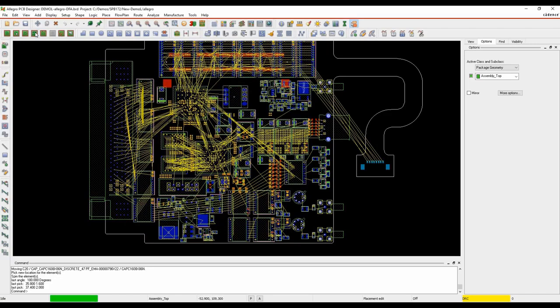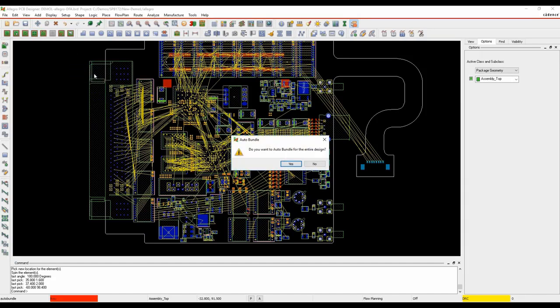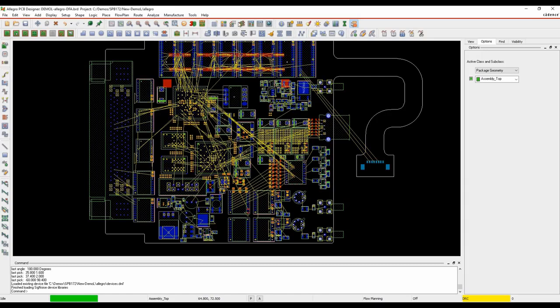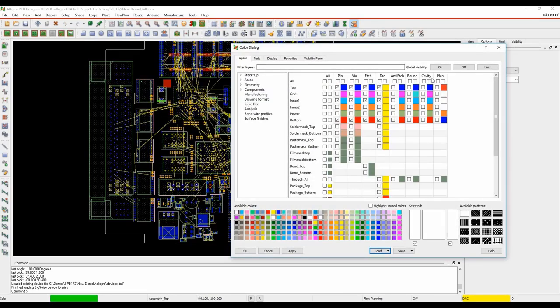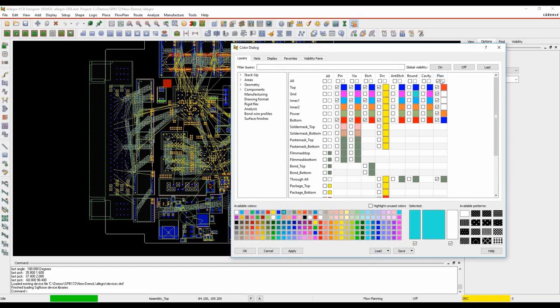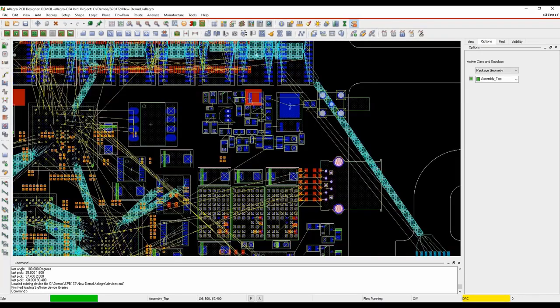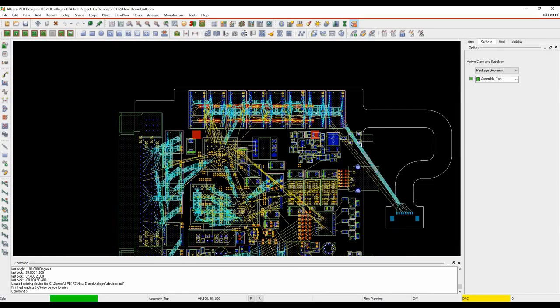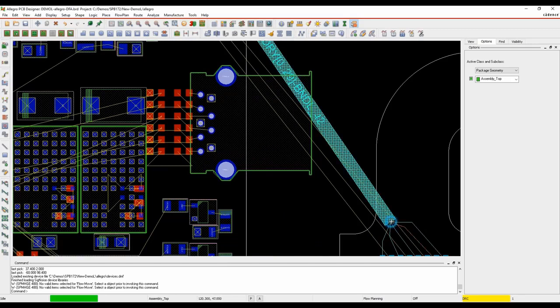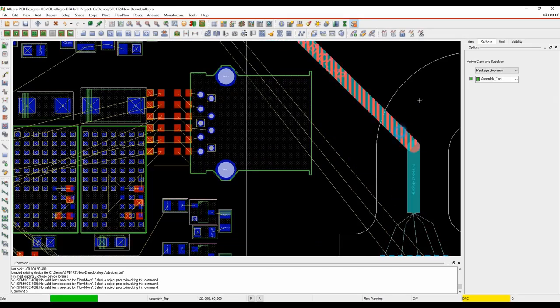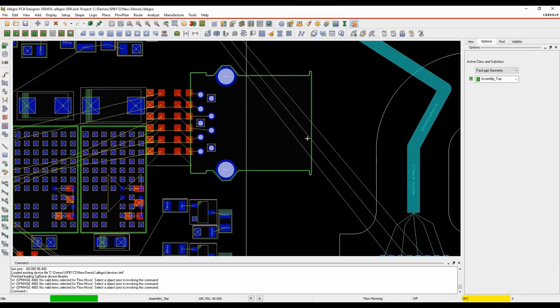But what we'll do is we'll go into IFP mode, or Interactive Flow Planning mode, and then I can just right click and auto bundle all, and we'll say yes to that, and all the bundles go. And if we go to the colours, there's now something called a plan. Let's specify some different colours for this. So you can see now I've got some bundle lines based on what I'm looking at from my routing. These can be dragged about, so I can grab the bundle and start to adjust how I want this to be routed through a board.